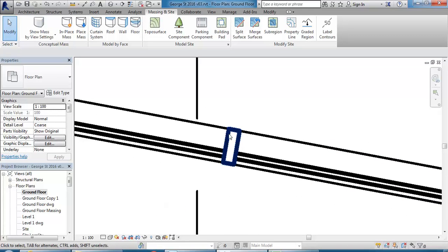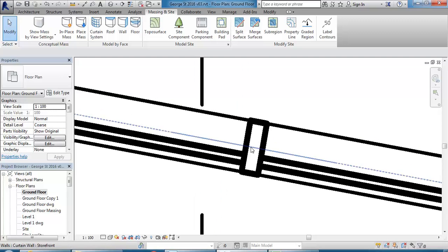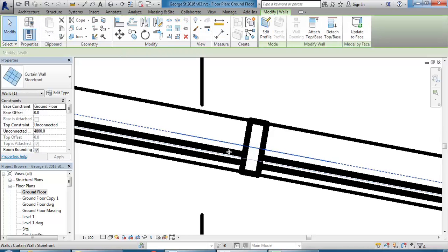So you can see then, firstly, when you see the glass next to a regular mullion, then it can make sense, or can make it clearer why the glass is set out from the centre line, because it's set up to work with this deep 150mm mullion, and it's set to go closer to the outside than the inside, which is the way you normally have glass in a window, so that it's easier to waterproof. And that's why the glass is set to go to one side of that centre there by about 30-something mil.